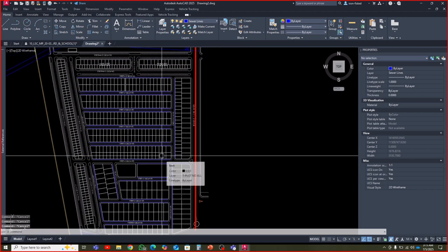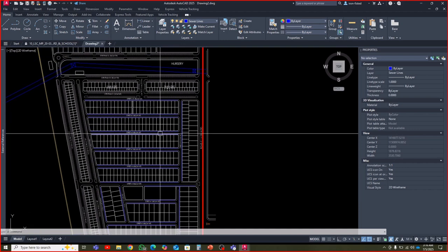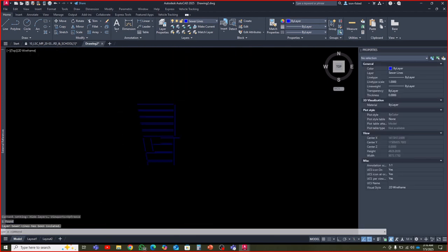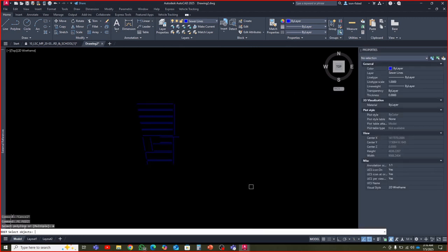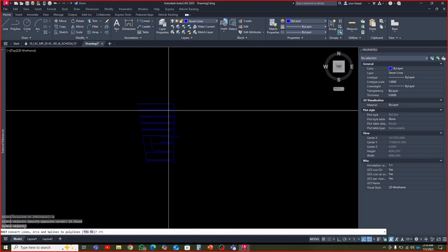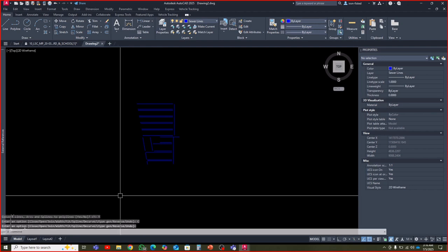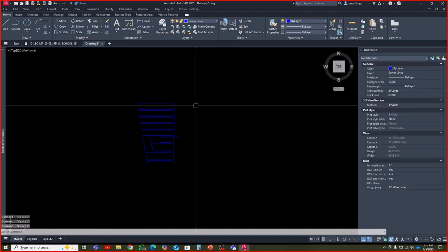Okay, so we have just created some lines. We need to convert them to polylines. Just go to edit multiple lines, select them all, and convert them into polylines, since we could use any other lines in SewerGEMS that are going to be replicated as pipes.